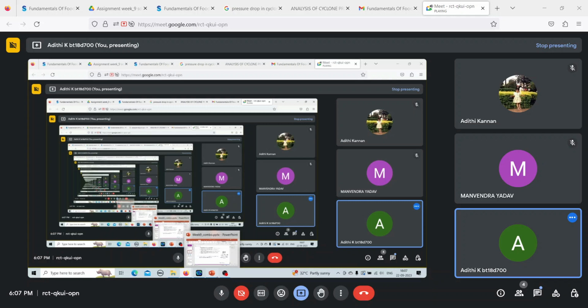So this represents that of a straight line where minus delta P is equal to Kv into V plus C, because everything else is constant, only the pressure and the volume of the filtrate keeps changing. Since this looks like an equation of a straight line, Kv or the slope can be given as mu alpha Cs dV by dt by A square, and the intercept can be taken as mu dV by dt by A into Rm. So your slope will have properties of the cake, your intercept will have properties of the filter media. Rm is due to the filter media.